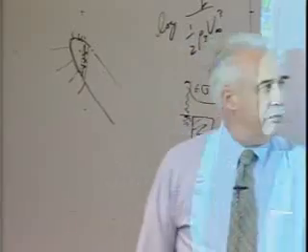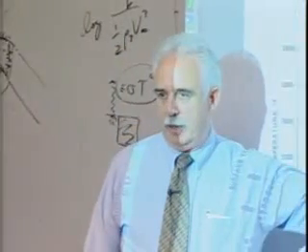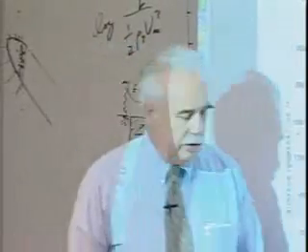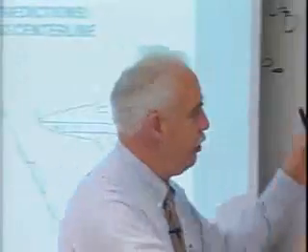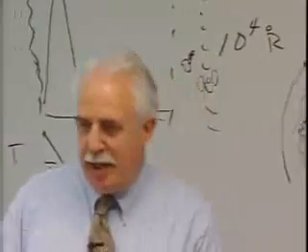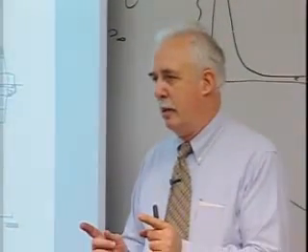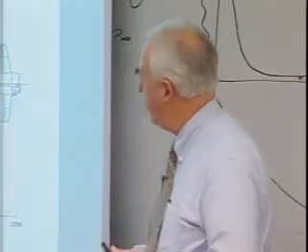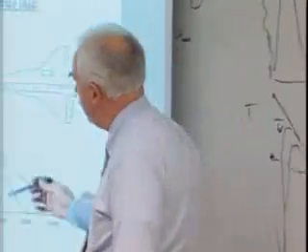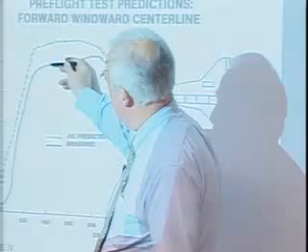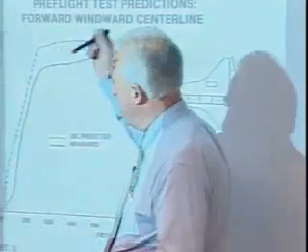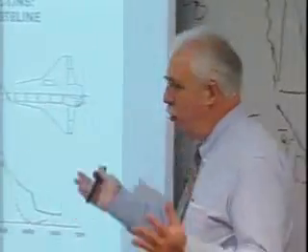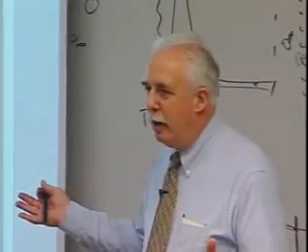See, we come much closer together here in time. This is predominantly the chemistry. At this time, this non-equilibrium relaxation distance is about 6 inches. Now, we're not into radiating gas, but we're certainly not into equilibrium. That is also a factor, and that is not well included even today, in my opinion, other than through correlations of the shock and what's going on here. You won't see that on paper because we did a terrible job there.